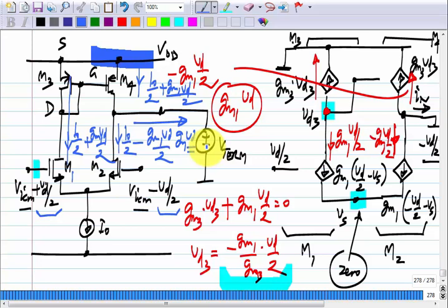Any questions? So, the Norton equivalent of the incremental equivalent of the differential pair, we have done half the job, we have calculated the short circuit current and that is just equal to GM1 times Vd, where GM1 is the transconductance of the differential pair transistors at the operating point current of I0 by 2. Is it okay? The result is very simple, but the derivation has to be done correctly, so that you have some confidence in the results.